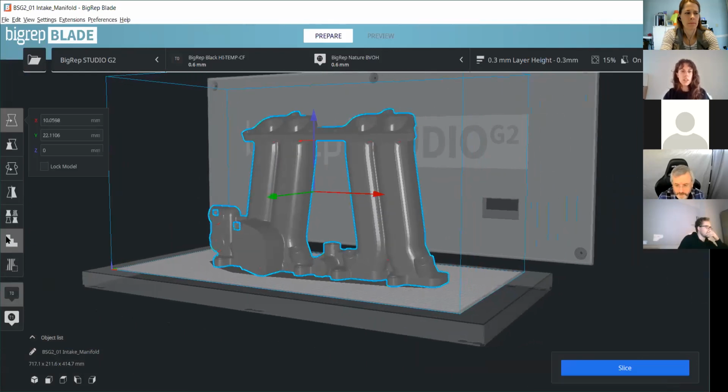And then over here, we actually have a manual support, a way to add support essentially. If there's areas where support is not being generated, usually this is used, like say you have a part that's thin, and you're worried about shaking as the print moves up, you want to add some additional support to anchor that print to the print bed. That's how you would do it.